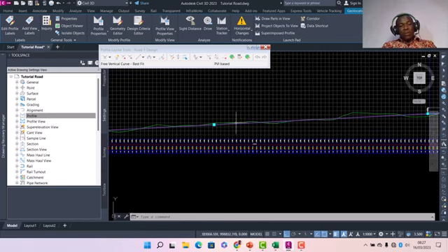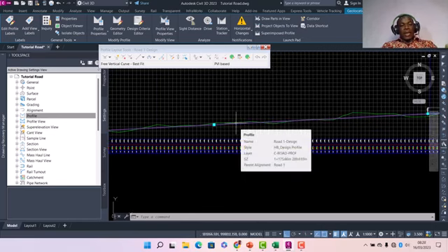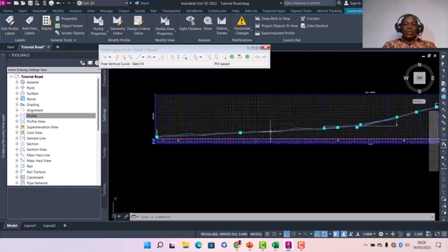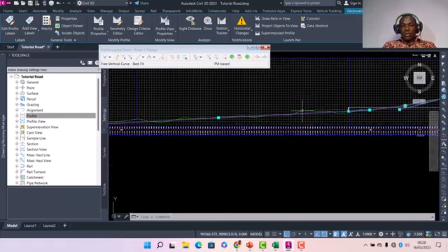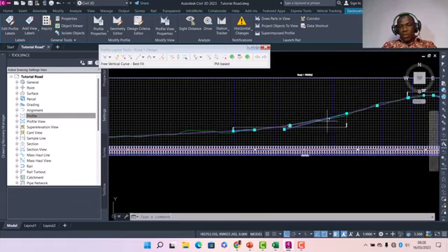here. In everything you are doing, make sure you are not less than 50 meters in tangent length. So you'll be checking that. Okay, so fine, I think this is cool. I believe you have learned a lot from this.